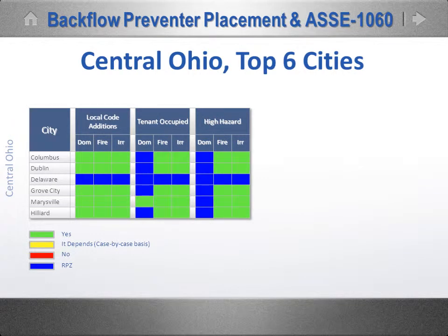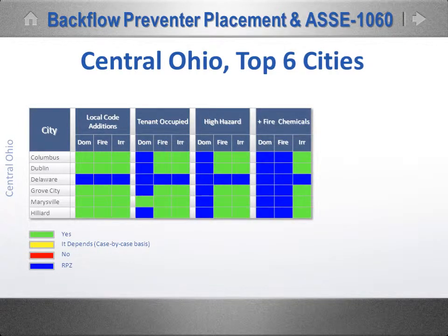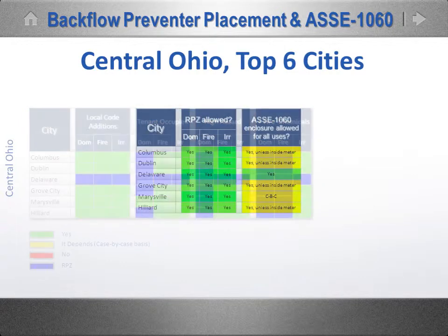Of course, when you add the conventional high hazard threshold requirement that we've all become familiar with, Marysville joins the other jurisdictions in the demand for an RPZ on the domestic line. Fire lines must utilize an RPZ anytime flame retardants or antifreeze are incorporated into the system.